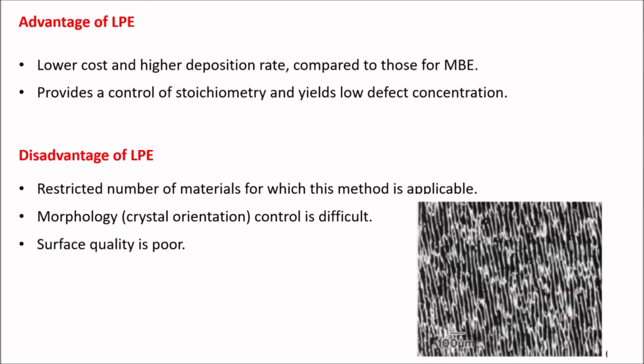Advantages of LPE include lower cost and higher deposition rate compared to those for MBE. LPE also provides a control of stoichiometry and yields low defect concentration. A disadvantage of LPE is that the solubility considerations greatly restrict the number of materials for which this method is applicable. Furthermore, the morphology control is difficult and surface quality is often poor.